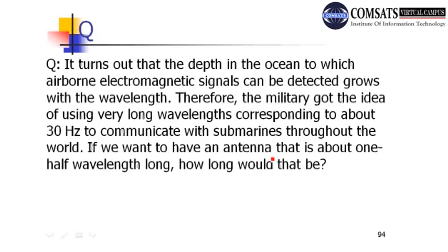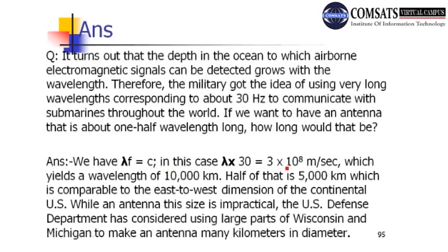Here we have another question. The depth in the oceans where airborne electromagnetic signals can be detected grows with the wavelength, right? So this is a different scenario. The military got the idea of using very long wavelength corresponding to about 30 hertz to communicate with submarines throughout the world. If you need an antenna that is about 1/2 wavelength long, how long would that be? Here we have to perform underwater digital communication.